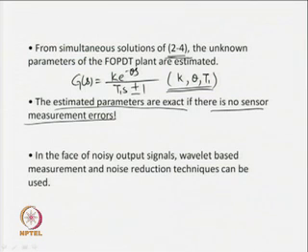That means, let us take this case, if the output is not error free, rather we get some output of this form, then one may not be able to make measurement of the slope. So, the slope information may be inaccurate. In that case, the estimation of k, theta and T1 may be erroneous. So, one must take care of this fact.